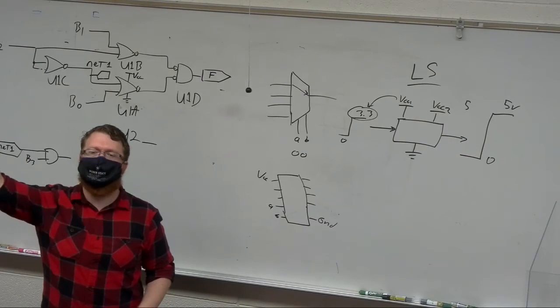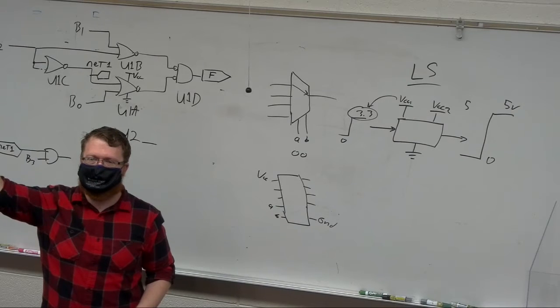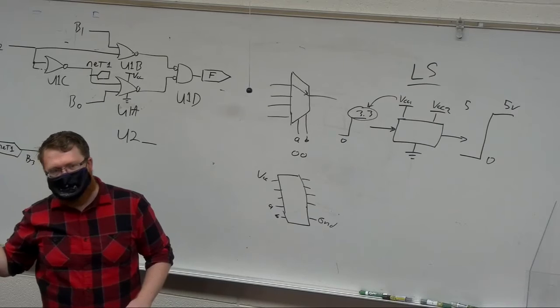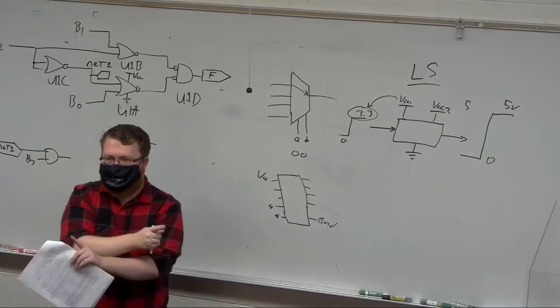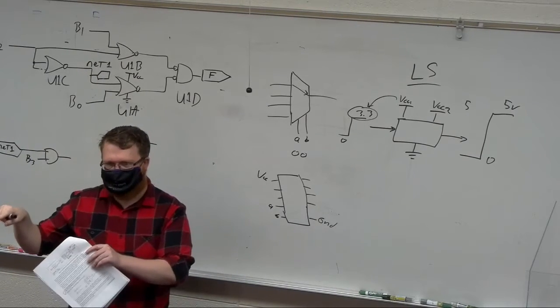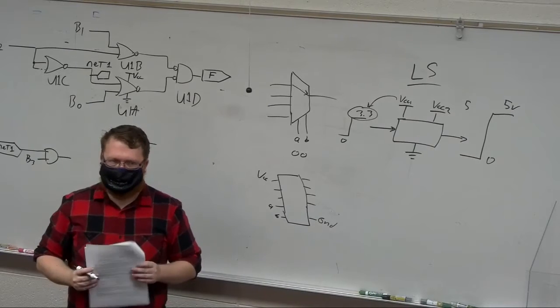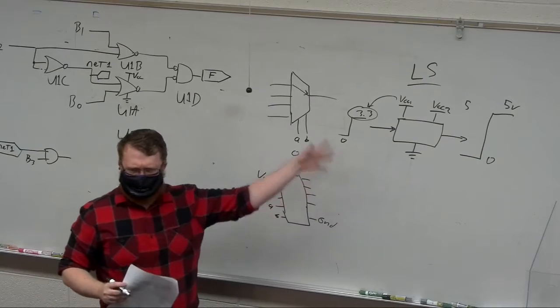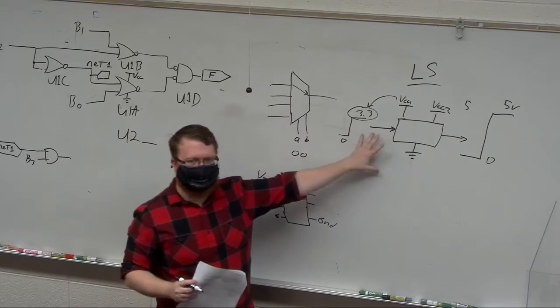So I don't actually have to go all the way to 5 to trigger it. But I do need to go all the way back to 0 to go back to 0, right? And so I could plug that in, but I can't go the other way because if I put 5 volts into a 3.3 volt, you're liable to break it.